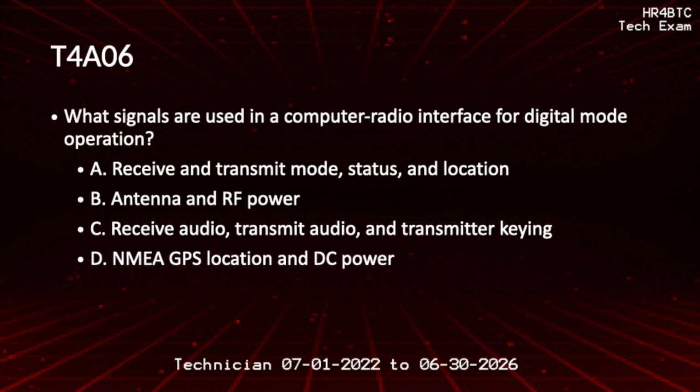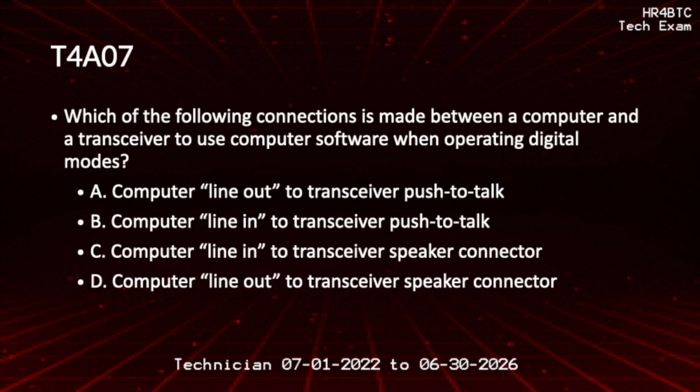What signals are used in a computer radio interface for digital mode operation? Receive audio, transmit audio, and transmitter keying. Which of the following connections is made between a computer and a transceiver to use computer software when operating digital modes? Computer line in to transceiver speaker connector.